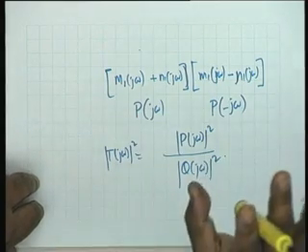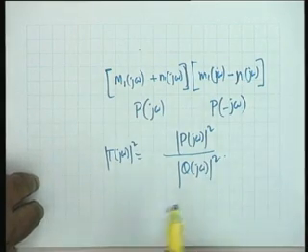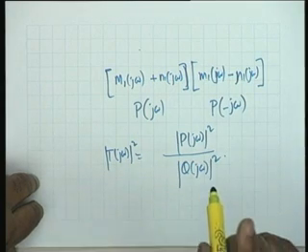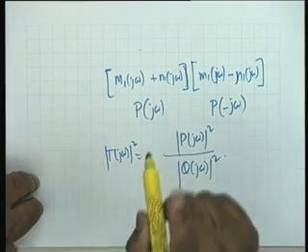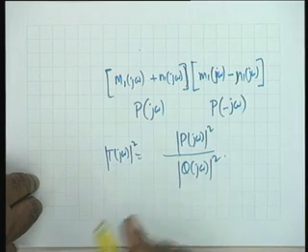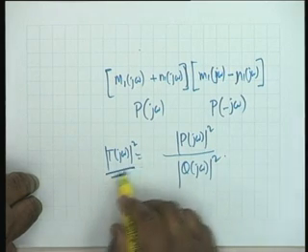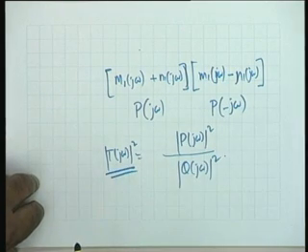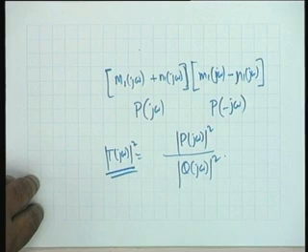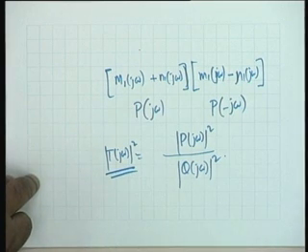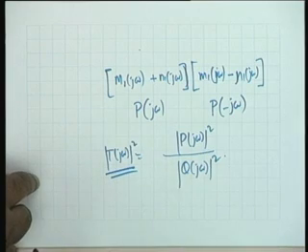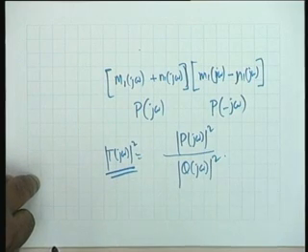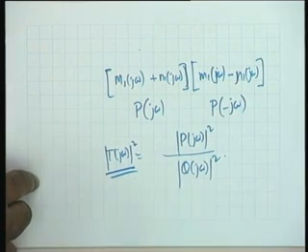The question that I am asking now, I have discussed this earlier. What can you say about this magnitude squared function? It must be purely even. Isn't that right? The magnitude squared function cannot be negative. It only contains even powers of omega in the numerator as well as in the denominator.